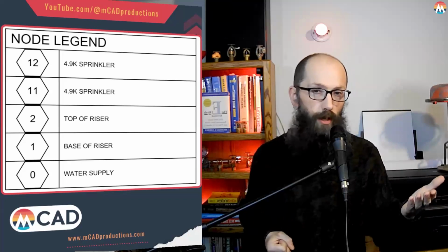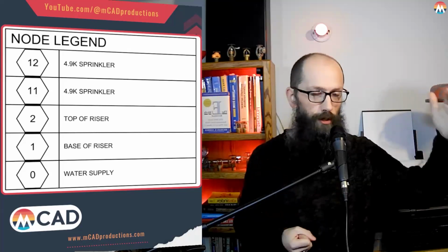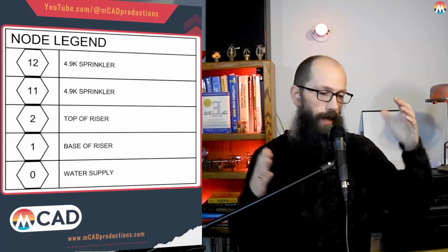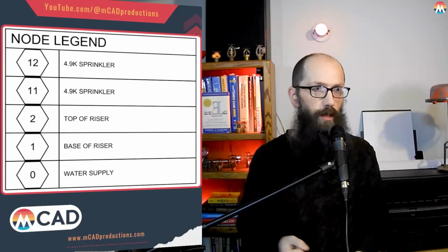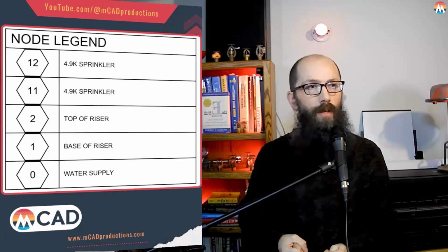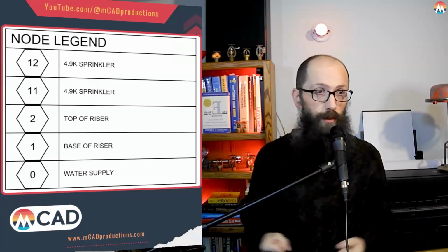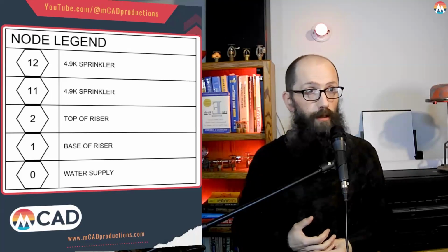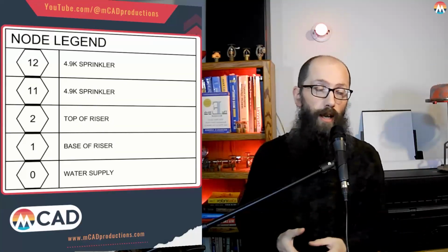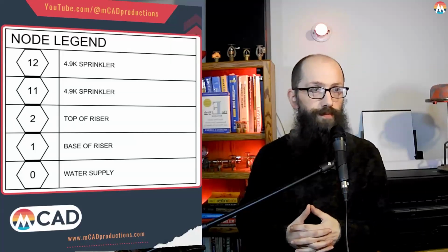There's always enough nodes in between 0 and your sprinkler number to account for all the changes that you need to input into your calc program. And on apartments, on a 3rd story calc, we do 31, 32, 33, and 34 on a 4-head calc for a 13R. So anyway, just ways of keeping the numbers straight and what they represent.